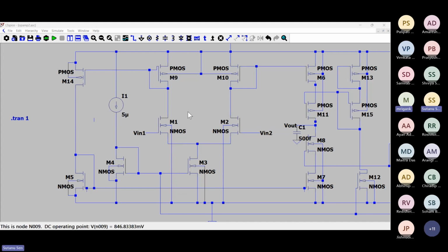So here we are getting it without it. Why are you mentioning that again? Sir, but the currents are not coming the same, right? But in that case, the DC currents were all coming the same, all 5 microamps. That is because the loading effect on both sides will be similar. The circuits are symmetric, so the channel length modulation effect on M6 will be the same as for M4. So the circuit becomes very symmetric, but that is not going to fix your phase margin issue. Phase margin will be worse because you are going to introduce two similar poles. So there is no advantage of going to this topology.